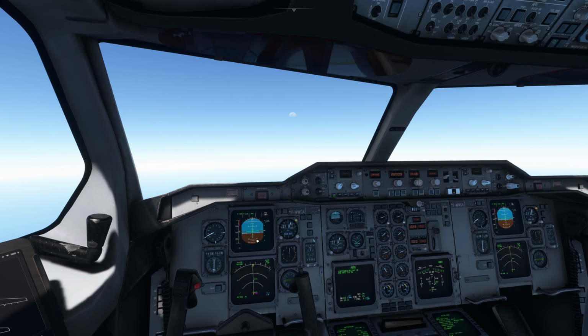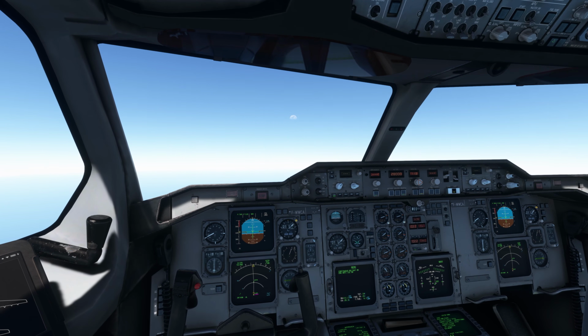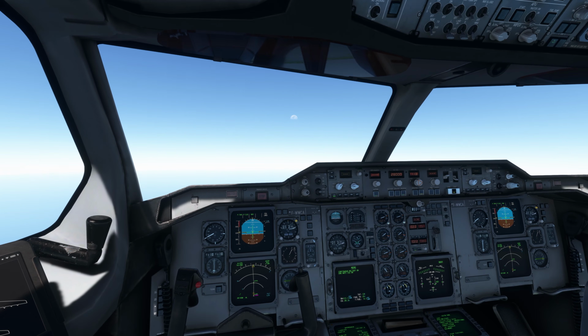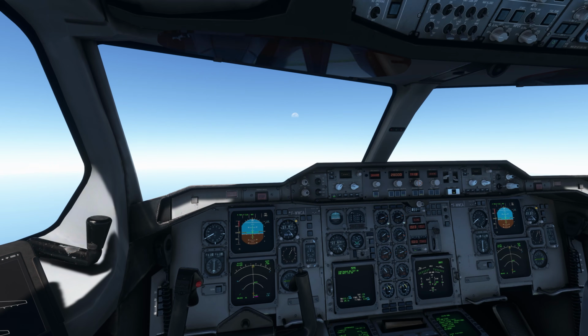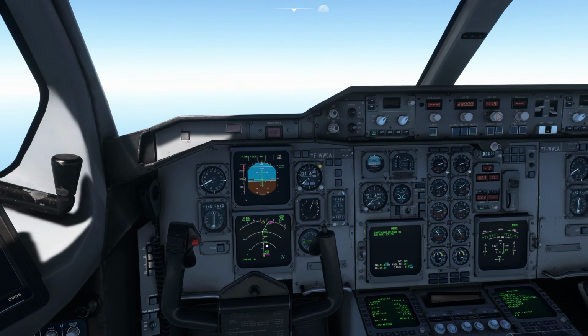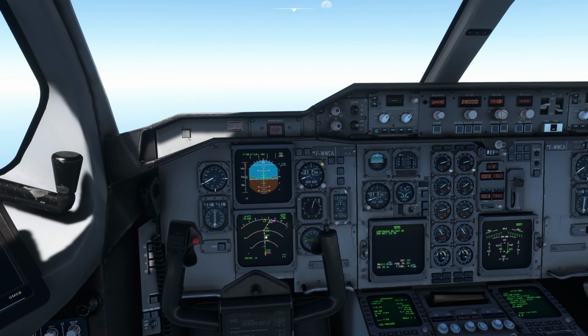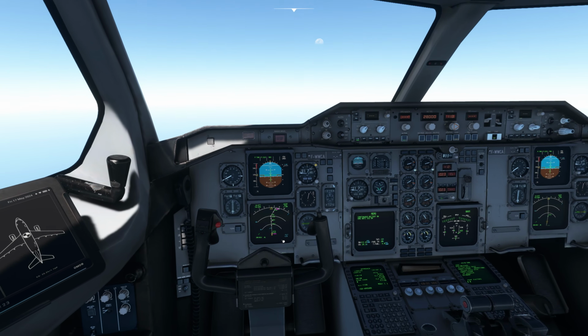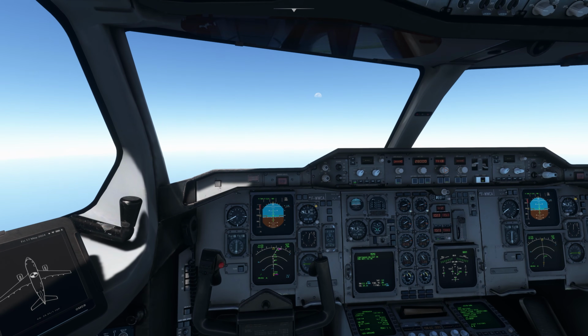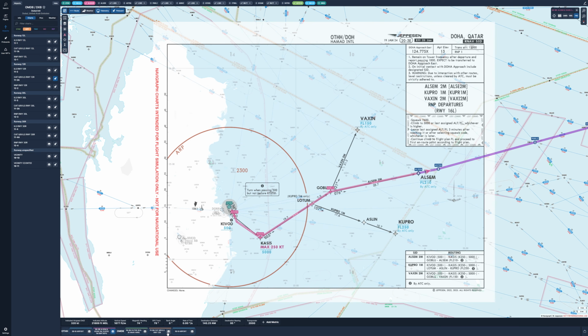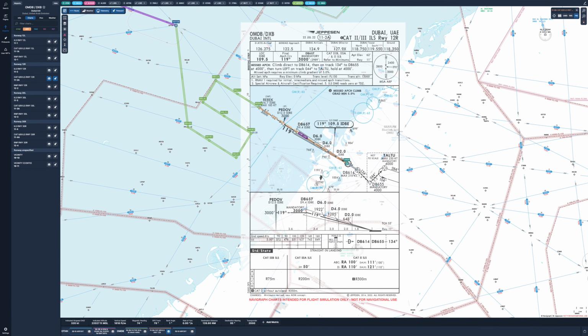Now as the plane is climbing to 28,000 feet, there are a few things that we have to do for the landing, because we have got a very short time during the flight between the top of climb and the top of descent. It will be coming over here on the navigation display. By this point the plane will be at 28,000 feet, and over here I have to start the descent. So first of all, let's see to which altitude I should be descending. Just go over here on the charts and look at the approach plate.